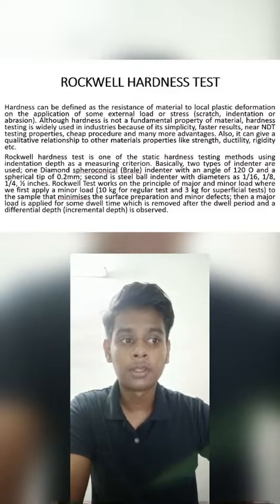Basically, two types of indenter are used. One, a diamond spheroconical indenter with an angle of 120 degrees and a spherical tip of 0.2 mm. Second is a steel ball indenter with diameters of 1/16, 1/8, 1/4 or 1/2 inches.